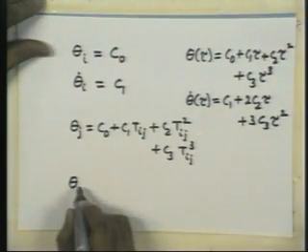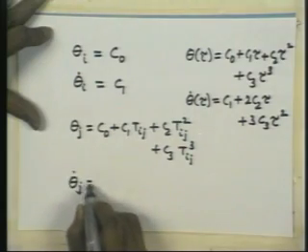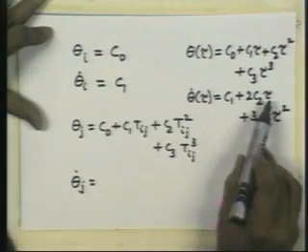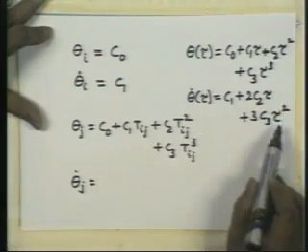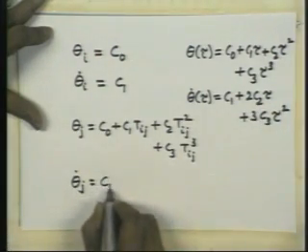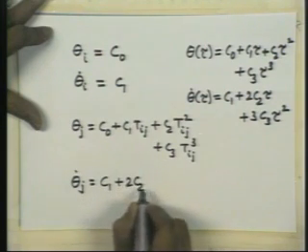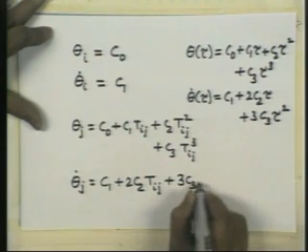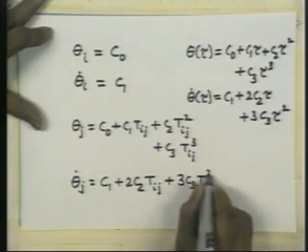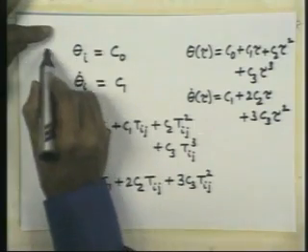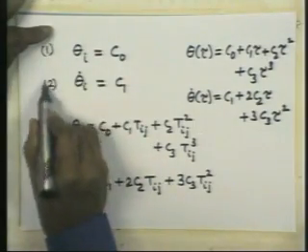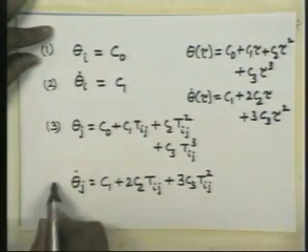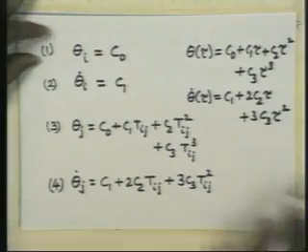And similarly, theta j dot is obtained by substituting tau equal to Tij in the equation for the velocities, and so theta dot j is C1 plus 2 C2 Tij plus 3 C3 Tij squared. Okay. So, I could call these equation 1, equation 2, equation 3 and equation 4. So, 4 equations to determine C0, C1, C2, C3.